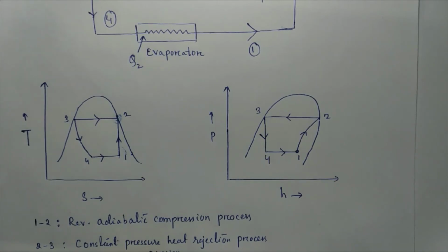And dry compression is always preferred to wet compression, because in wet compression there is a danger of the liquid refrigerant being trapped in the head of the cylinder by the rising piston, which may damage the valves or the cylinder head. The droplets of the liquid refrigerant may also wash away the lubricating oil from the walls of the cylinder, thus increasing the wear in the compressor. So that's why dry compression is always preferred in comparison to wet compression.